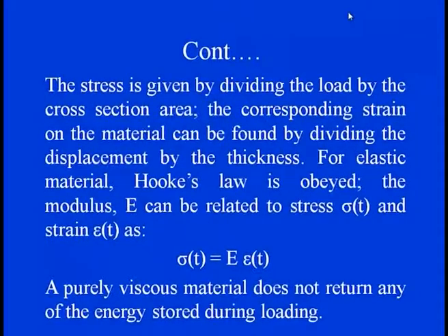So the stress, which is time dependent, sigma of t, is proportional to the strain, which is also a time dependent phenomenon, as we discussed already for the viscoelastic material. So sigma of t is proportional to epsilon of t, and when we make it equal, we have the Young's modulus of elasticity.